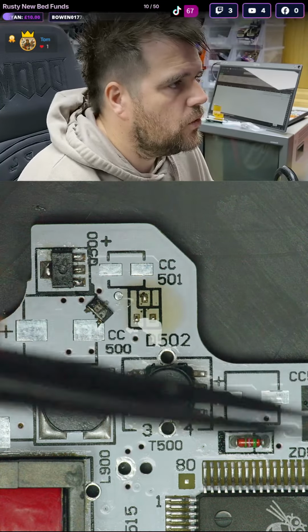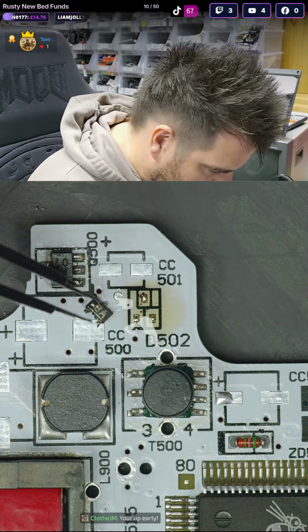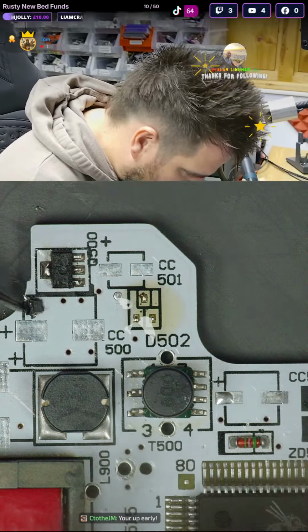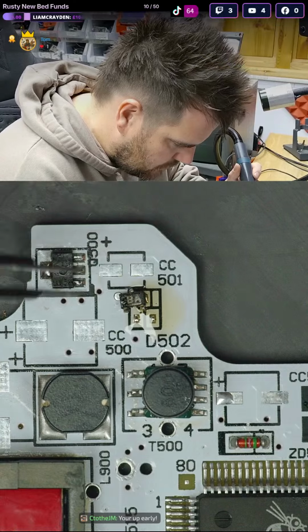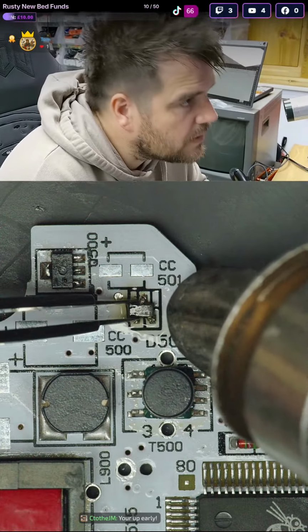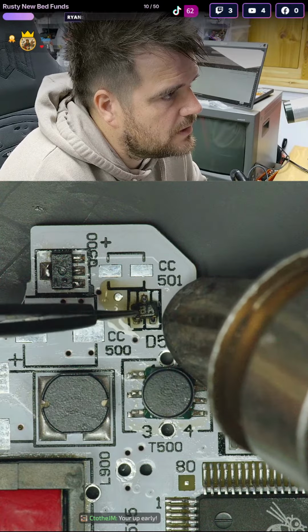And if it wasn't for the fact it says D502 here, we might have been tricked into thinking that was a transistor, but I did notice afterwards that it showed up as 0 current passing through the transistor, which was a hint that it wasn't a transistor. Might have been a quicker way to identify the diodes as well.